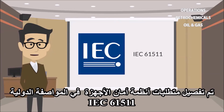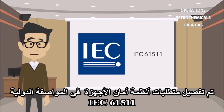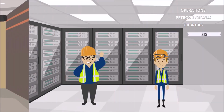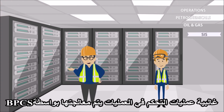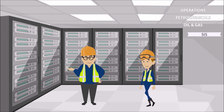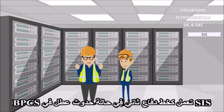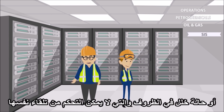The requirements for safety instrumented systems are further detailed in International Standard IEC 61511. This is the standard for safety instrumented systems for the process industry sector. A majority of the process control operations are handled by the BPCS. The SIS acts as a second line of defense in the event of a failure on the BPCS or an upset condition that the BPCS cannot control on its own.